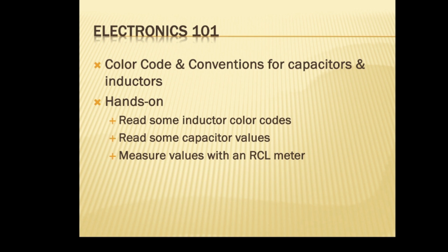You also have a color chart for inductors. The colors are essentially the same as for resistors or capacitors, i.e. brown is 1, black is 0, red is 2, etc. But these are generally a little bit easier to read than the capacitors are. Capacitors can be so tacky. There's so many different standards for capacitors. So anyway, everybody take a couple of those, and we're going to look at them and see if we can read the values, and then we'll try to put it on the LC meter and see what it says the values are. Why is everything so tiny?